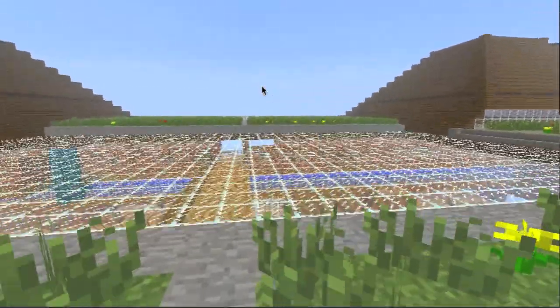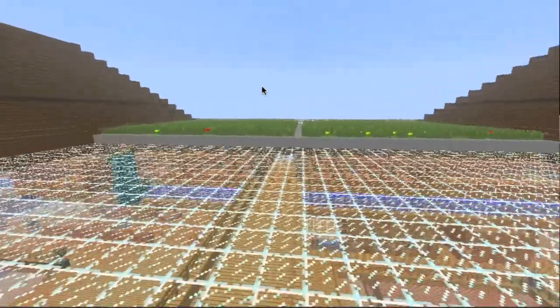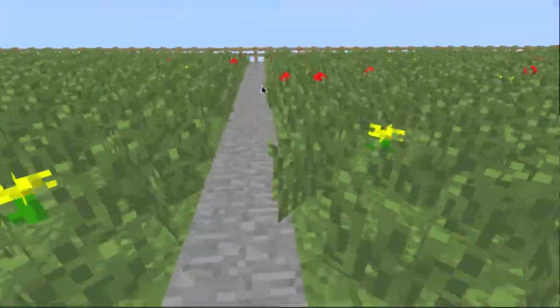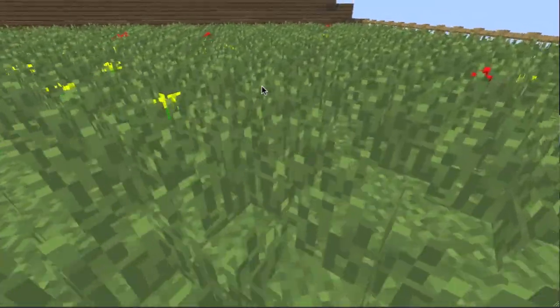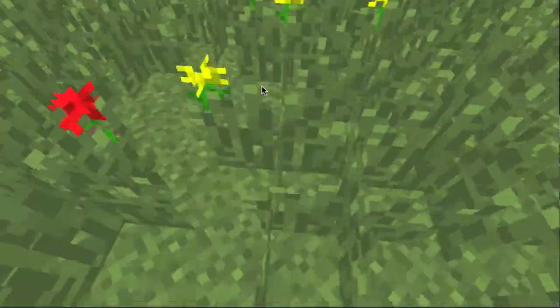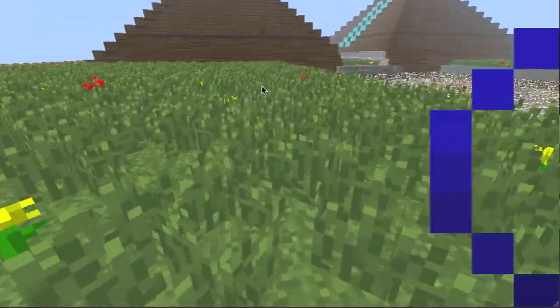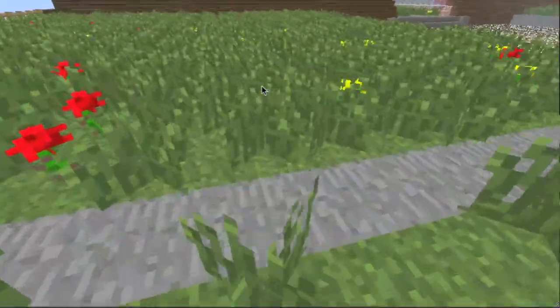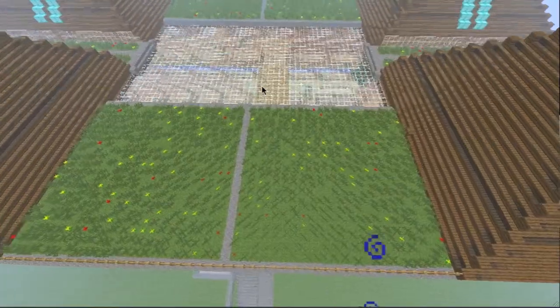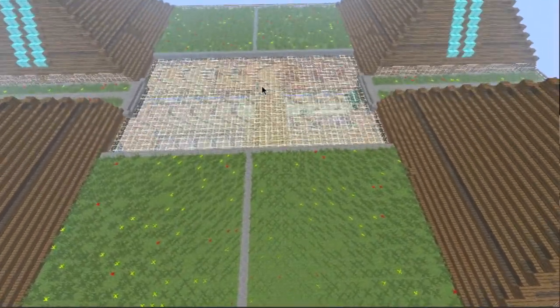It is also proven that in summer, the temperature beneath a membrane of a normal roof is 32 degrees, while beneath a membrane of a green roof it is 17.1. Also, in winter, under a standard roof membrane it is 0.2 degrees, while under a green roof membrane it is 4.7 degrees. Here, you are saving quite a lot of money.